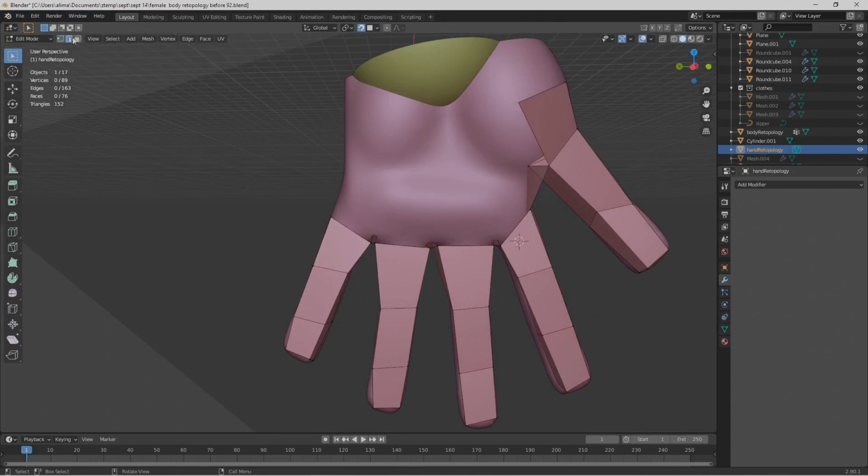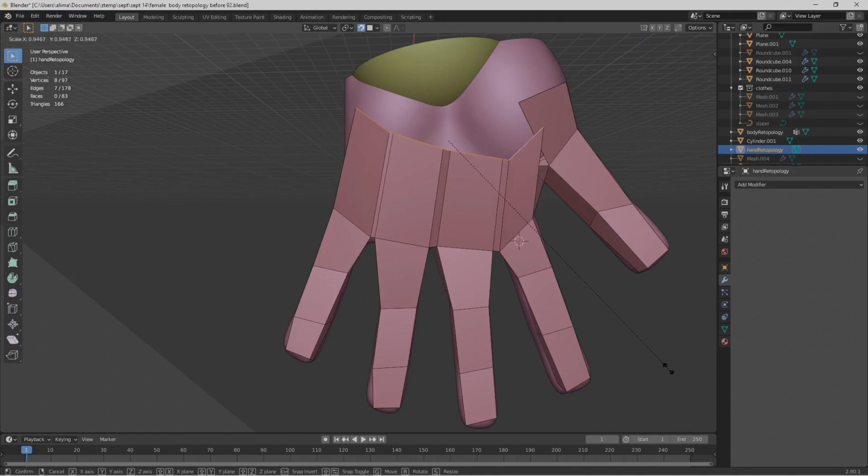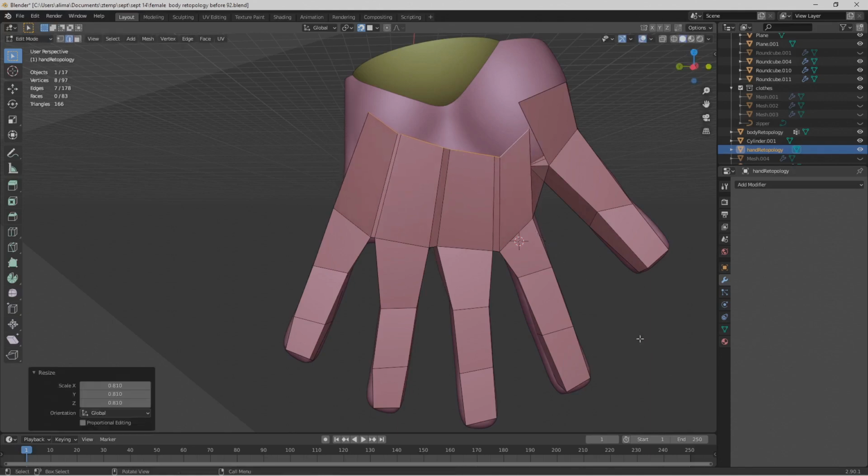So I'm going to go to the upper left, go to Edge Select, select here, hold Control, then select here. I let go of Control. I used Blender's shortest path technique. I'm going to hold Control, then right click. I'm going to move my mouse a decent amount away from the selection, so I can press S to scale. Then I'll left click to confirm. I'll then press S to scale on the Z axis 0, then left click to confirm. I'll then hold Alt, then press B to reveal what we previously had hidden.